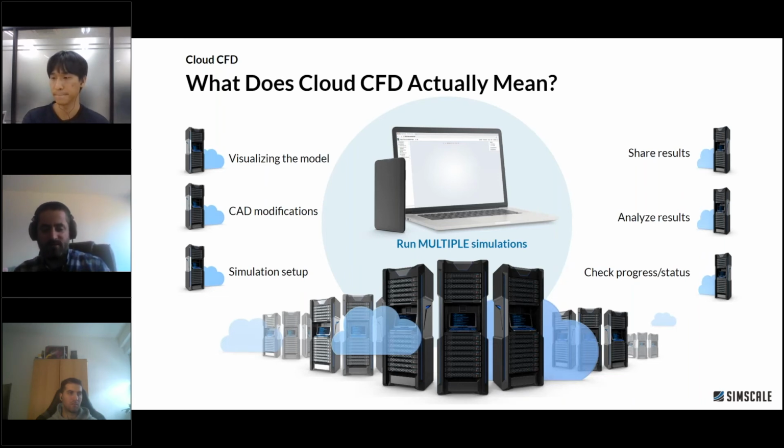And during this process, all of these steps that you see here have different requirements for you in regards to software and hardware, right? Visualizing the model and analyzing the results essentially need a good GPU. You want to really render this model fast and have valuable insights. On the other hand, putting together the simulation setup does not really have high requirements in regards to CPU and GPU power at all, while on the contrary, once you're running your simulation, or even multiple simulations, you really now need the power, you really now need the hardware.